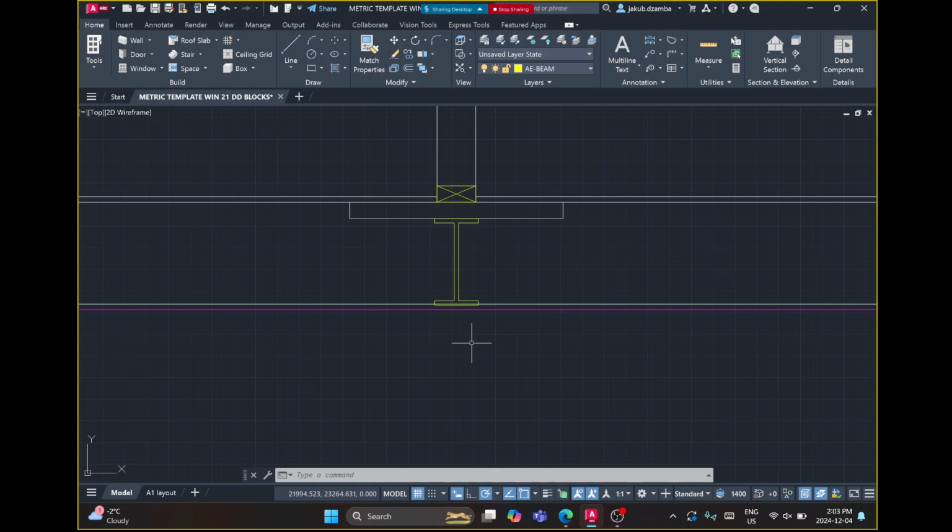So there's an I-beam going this way across the house, and it's supported on columns. So draw the I-beam. They have theirs actually a little bit lower. Theirs goes below the beam. But I'm not sure, like 100 by 200 is a standard size, so I don't know what size they're using. And since they don't give us any details, we're going to go on our own. And so we have our I-beam, and now I'm simply going to draw a column below it, going right down to the concrete floor.